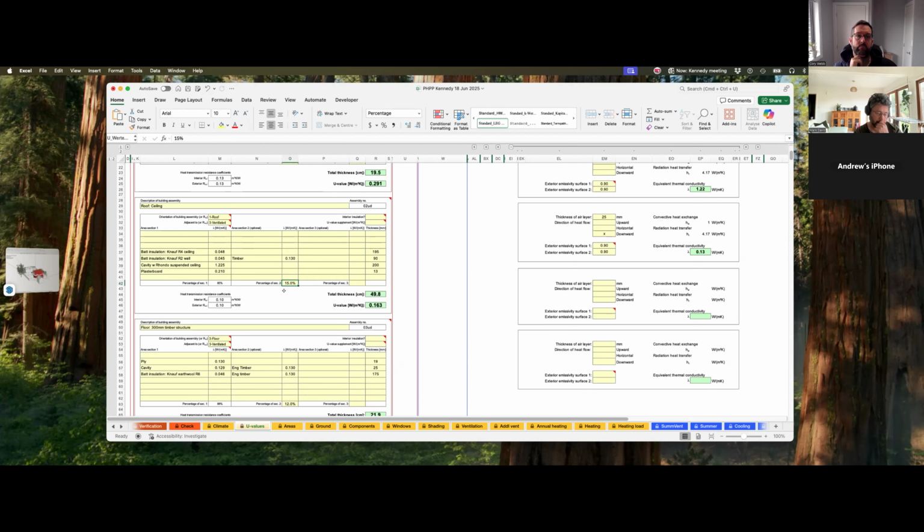So what I'll do is I've got a link I think I can send you, which should show you one of the main methods of doing it. Basically, what you do is you put a small hole in your membranes, and then you put tape folded up from the membrane onto the cable.